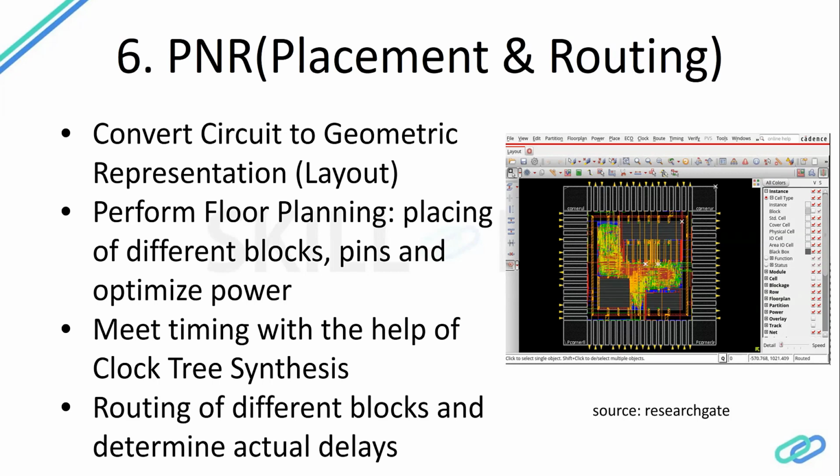Further, you need to do floor planning, which is nothing but placing the different blocks which have been generated by the tool relative to each other, so that you can optimize the power and best reduce the area. You again need to fix the timing with the help of clock tree synthesis. Then routing has to be done for different blocks and you need to determine the actual delays.